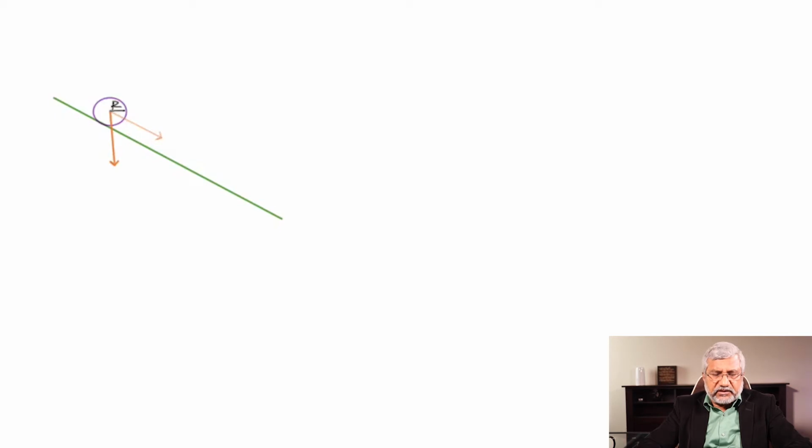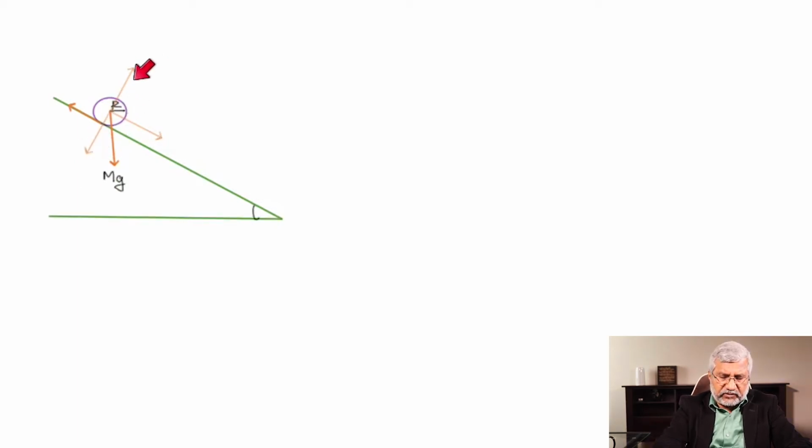So this is a free body diagram coming up. You see the weight of the object acting down, and you have this component along the slope and the other component perpendicular to it, and then you have the normal reaction which is equal to this, and this is friction. Friction acts tangentially between the surfaces in contact, and it's opposite to the motion. And actually it's friction that causes a torque.